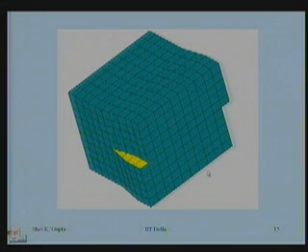And you notice here, you don't see any problem with the crystal. It's a perfect crystal. Every unit cell is a square, no distortions. Distortions are only in this part. If I look at here, each one of them is a square, but maybe slightly tilted with reference to these squares. Some kind of shear has taken place here, and a shear has taken place in this region. As I go away, these strains will also not be visible. I have shown it purposely here just to demonstrate that something is happening. But when I go away some 10-20 planes, I will not see those strains. It depends also upon the nature of the bond.